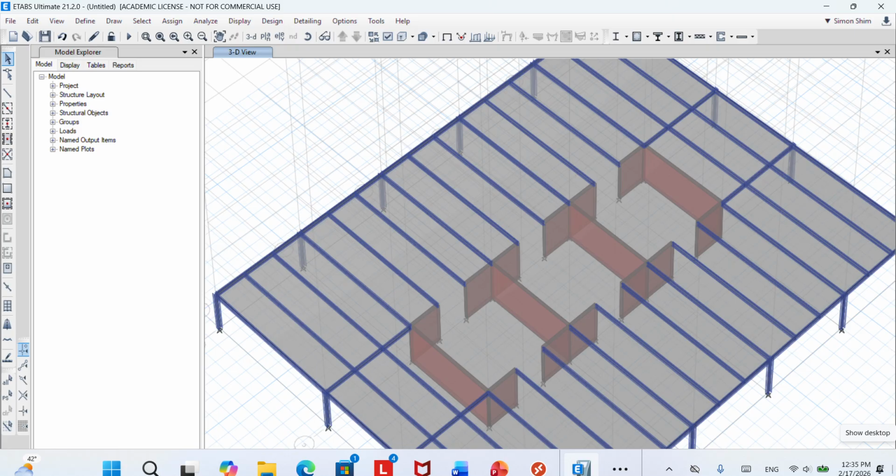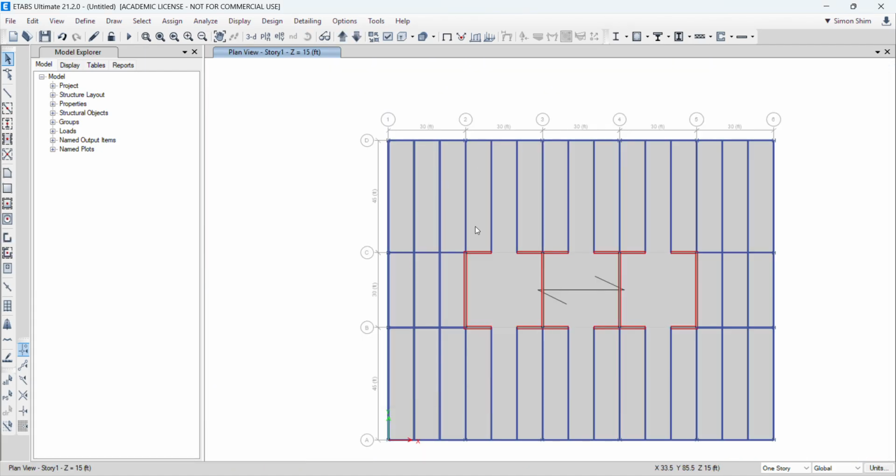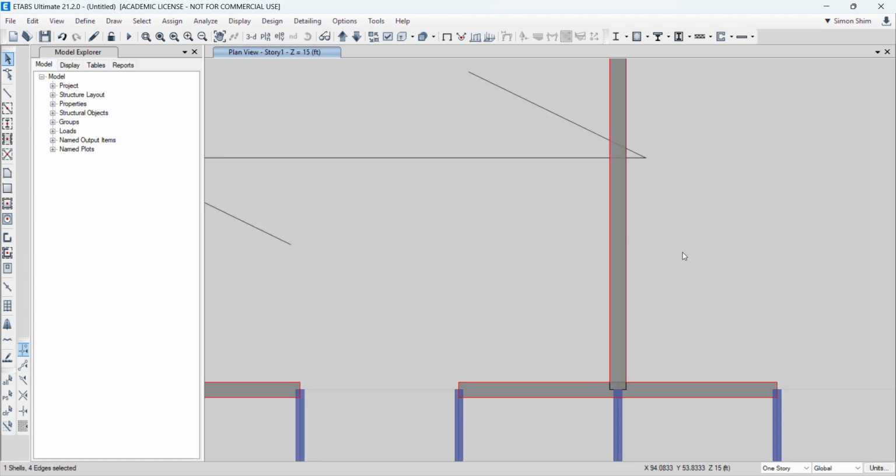We're going to tie it with the concrete beam because the wall is a vertical element and has to be braced together. So we're going to add a concrete beam. I'm going to go back to story one and zoom in, and draw the concrete beam as well. Why doesn't this zoom extend work?